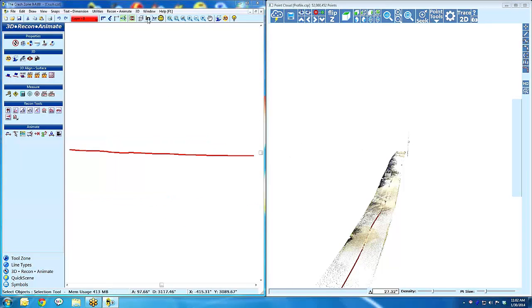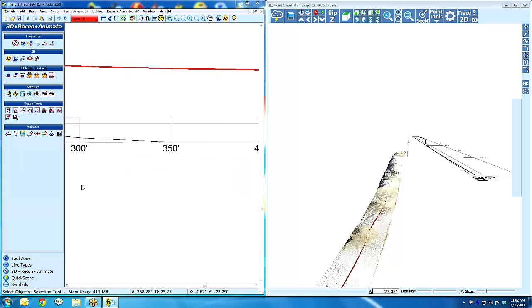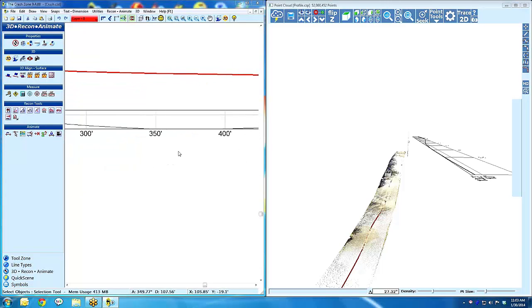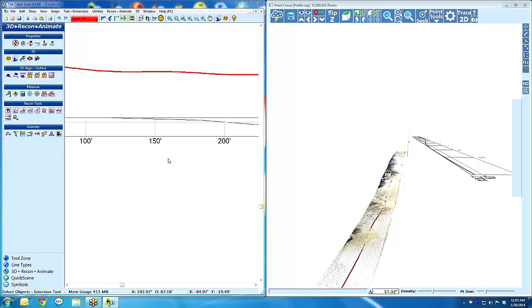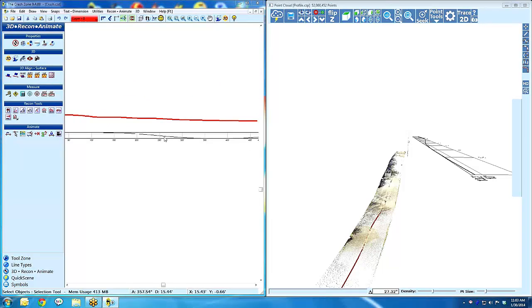All I have to do is delete it, go up to the settings here, go into feet or feet and inches, select it. Really takes no time at all just to hit the profile tool again, drop it in, and there you can see the entire profile and the entire travel or distance along the profile for line of sight maybe, or you got your side view here.